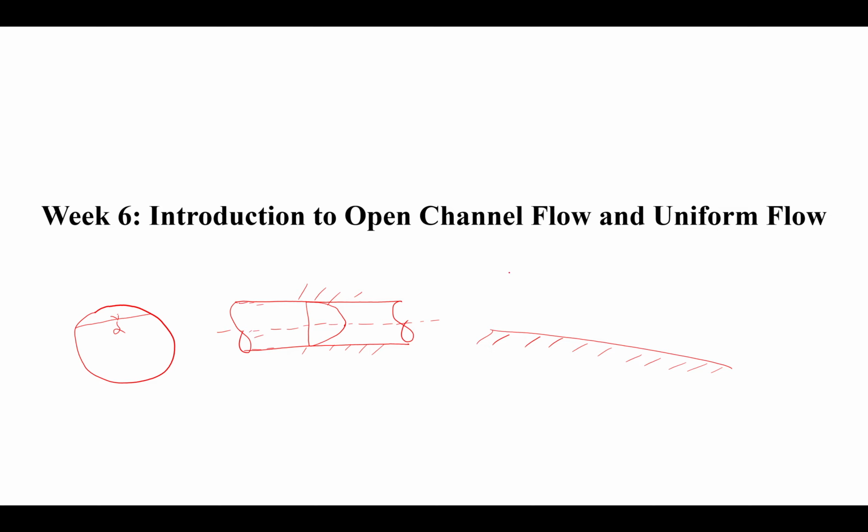In case of open channel flow, if water is flowing in this direction, your velocity diagram looks like this. Here, due to the dip phenomenon, the velocity will be a little less from this location. The dip phenomenon is due to the air and the secondary circulation. So that's all about the velocity diagram.